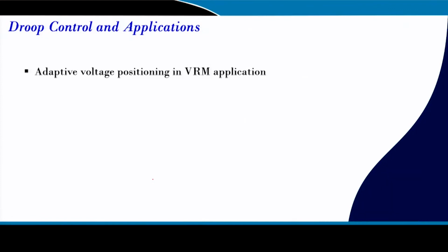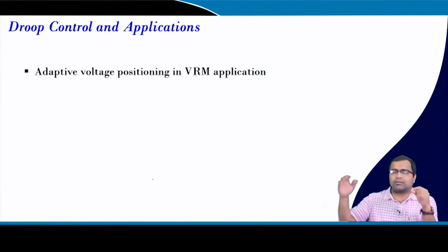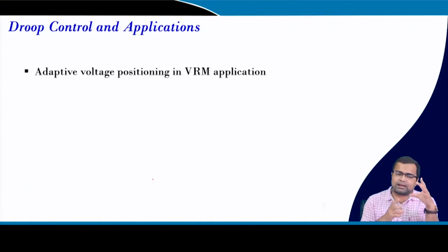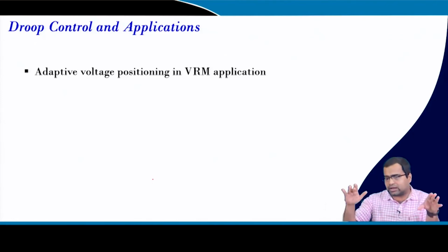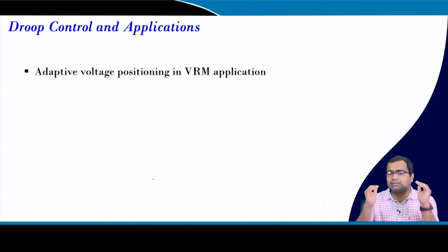And if there is a 100 ampere load step change, there will be a jump due to the ESR, and if it again needs to go back, that may take more time, and even if we apply a high gain, the current overshoot can be pretty high. So, this process can cut down the current overshoot, and it will also remove the transient effect, but the penalty is it will shift the DC regulation point a little bit, but if it is within the acceptable limit, then it should be okay.